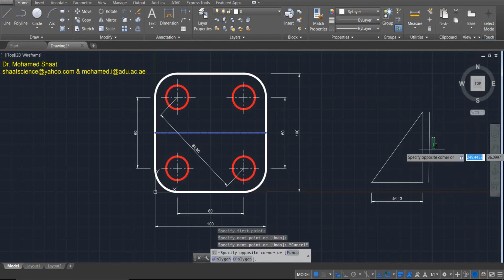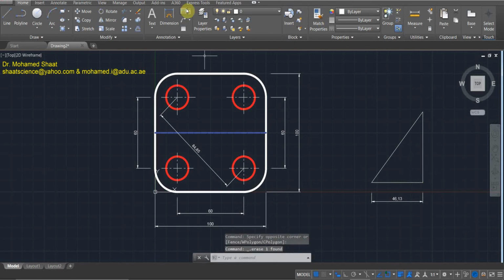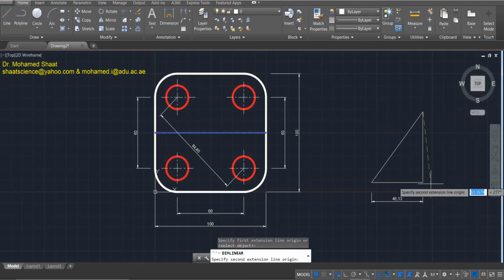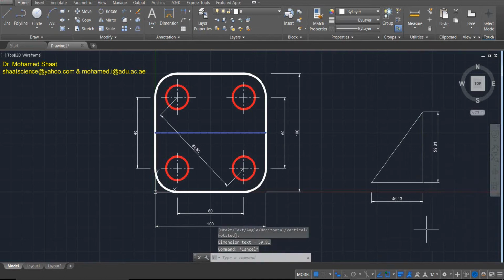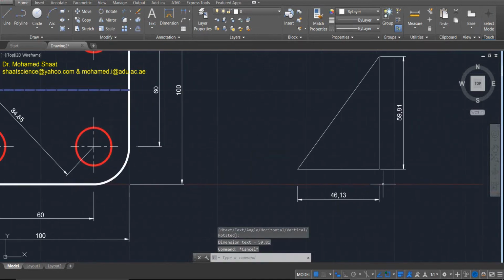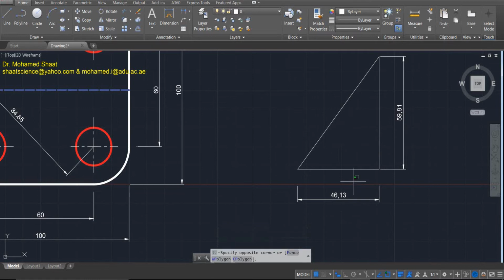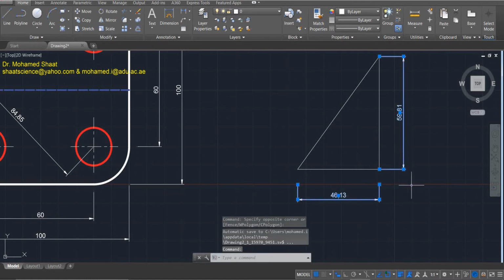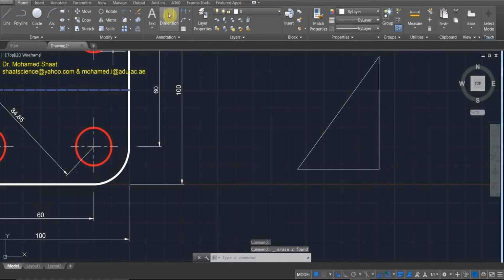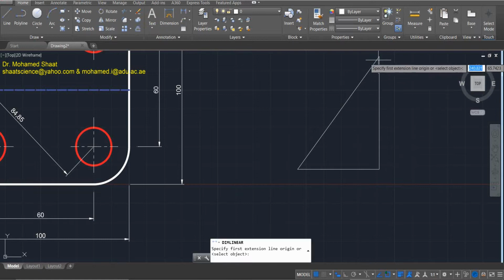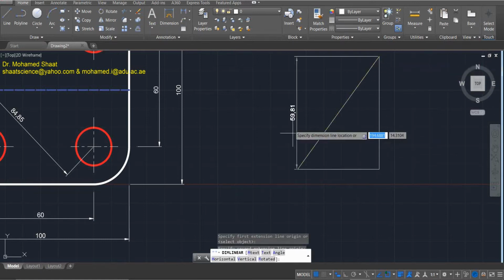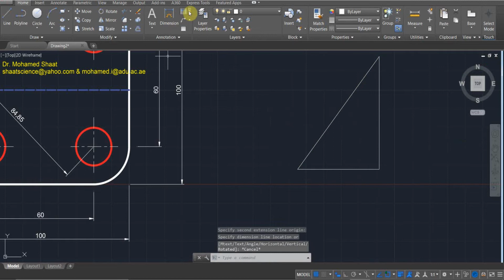This is what we used to define for the dimensioning, right? Before, I draw a line. It should be dimensioned between these 2 points, right? So we used to add the dimensions for any inclined line as a horizontal dimension and a vertical dimension. The other option is to replace these two with an inclined line by giving the length of this inclined line. You're gonna define the length, but in this way.